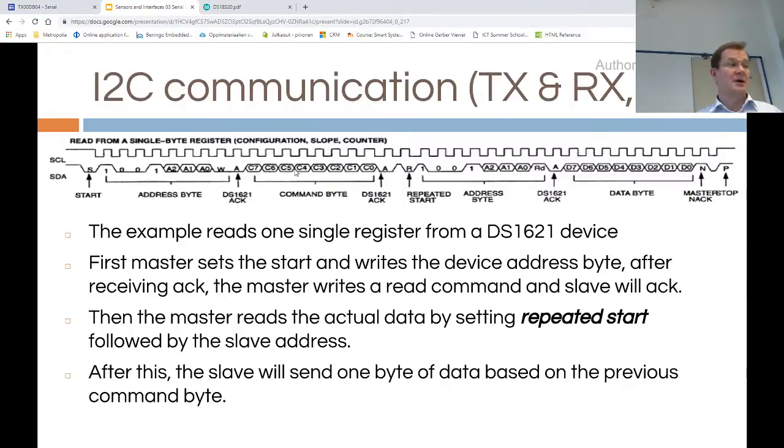For example, with I2C memories, you first write the address for the memory pointer on the I2C EEPROM, and then you start reading from that forward, one page at a time.